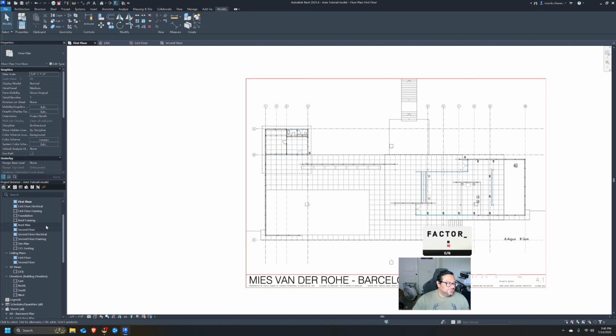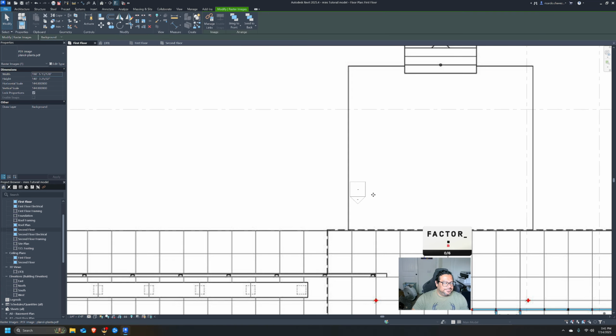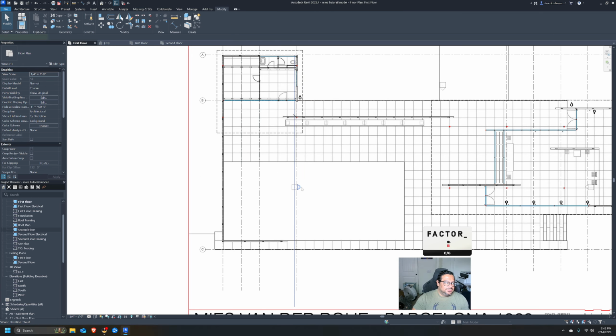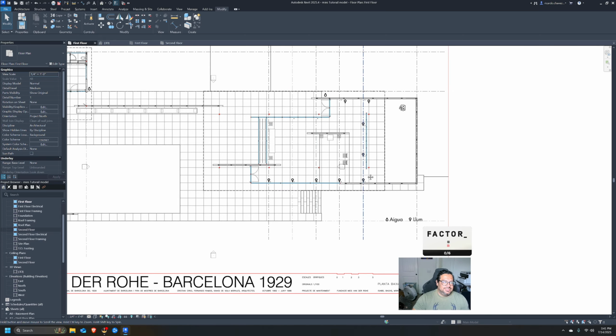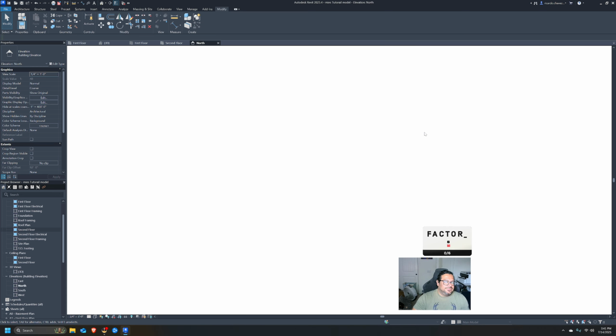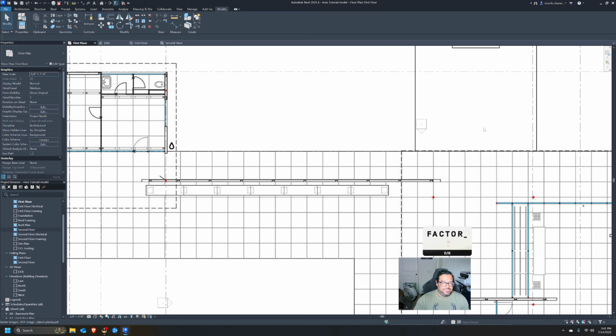The way we do that is usually you can go to an elevation or a section. We have some elevations here, so it's a good way to talk about it. Elevations are basically, you saw in 3D, we can see a 3D model. So as you're working on your 3D model, you're basically setting up elevations as well. They're automatic. The elevations usually will be these square boxes you see here. If you click it now, you don't see anything because we haven't built anything, right? So here's your other one. There's nothing there yet because we haven't built anything. But if we do a wall here, for example, you click on this elevation, there it is. So elevation controls the height of everything in your project.